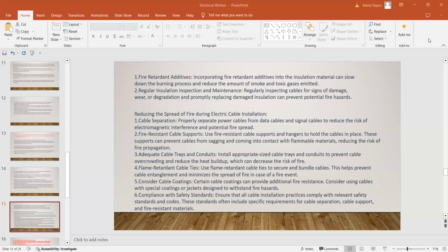And for the control circuit, especially for the generator, we are changing this cable five yearly, correct? Rest all depends on company to company how they want to go about it, but some good companies are changing this cable five yearly, especially on the control circuits of the generators.